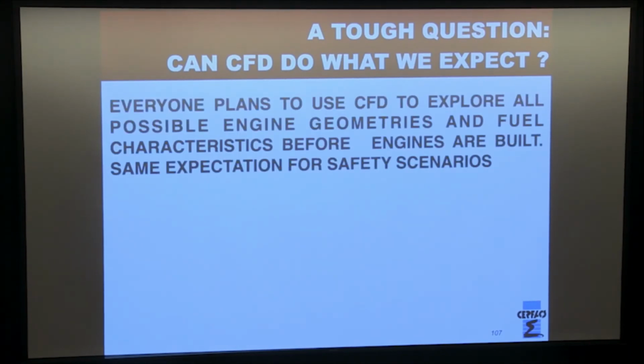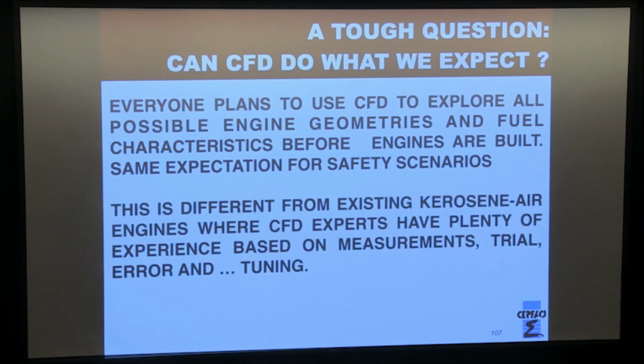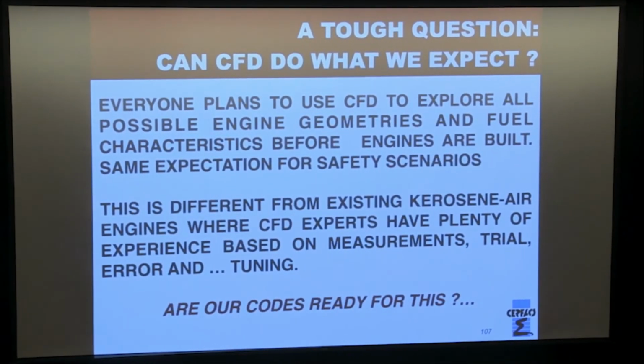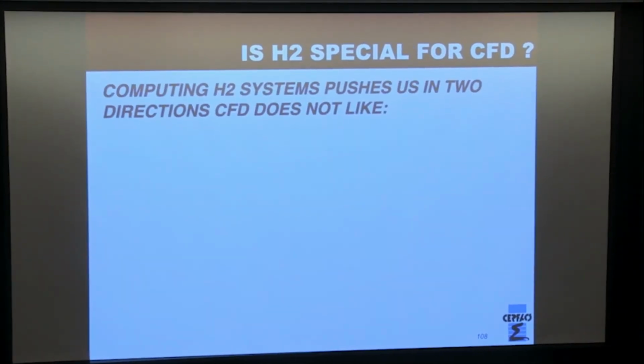So, of course, everyone plans to use CFD to study these scenarios. And as I said, remember that there are constants in all the models that we've been using for turbulent combustion. These constants have been tuned in the last 20 years for kerosene, for methane. But when we go to H2, things are so different, the regimes are so different. For example, you might move from premixed to diffusion flames. Now you have to redo everything. And that's going to be a tough question.